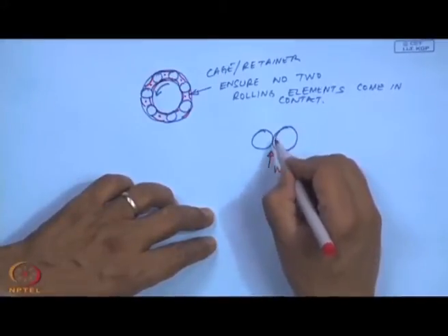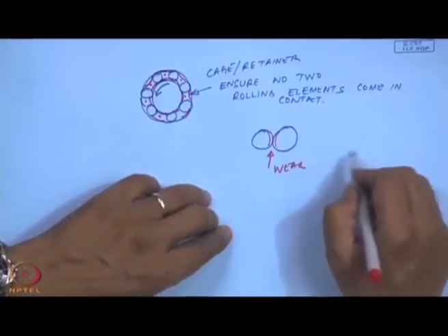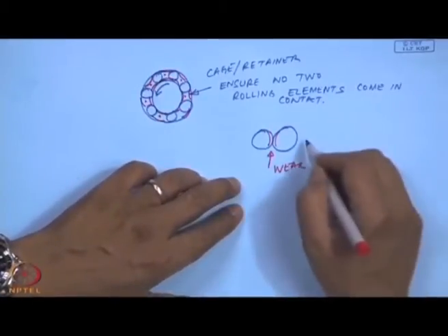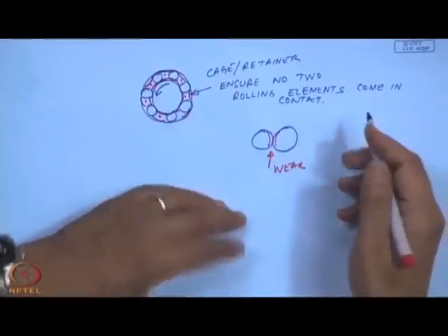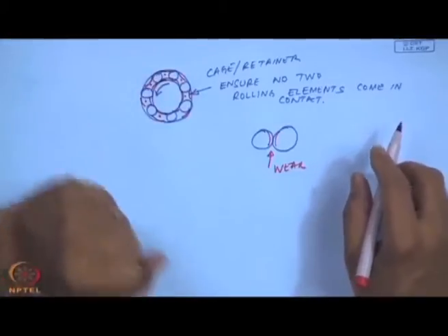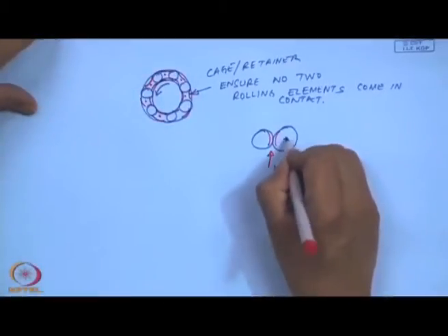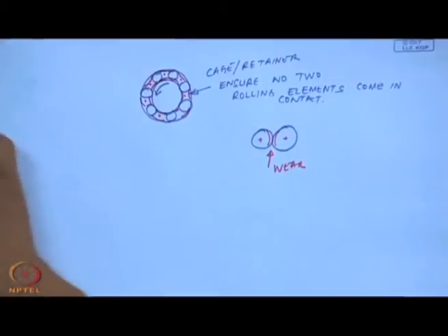They will get deformed, okay, and then they will not be perfectly round, and then they will have more friction, and then more noise, more vibration. And that is what brings us to the next topic, rubs. Okay. And if these things are rotating, we should avoid rubs.